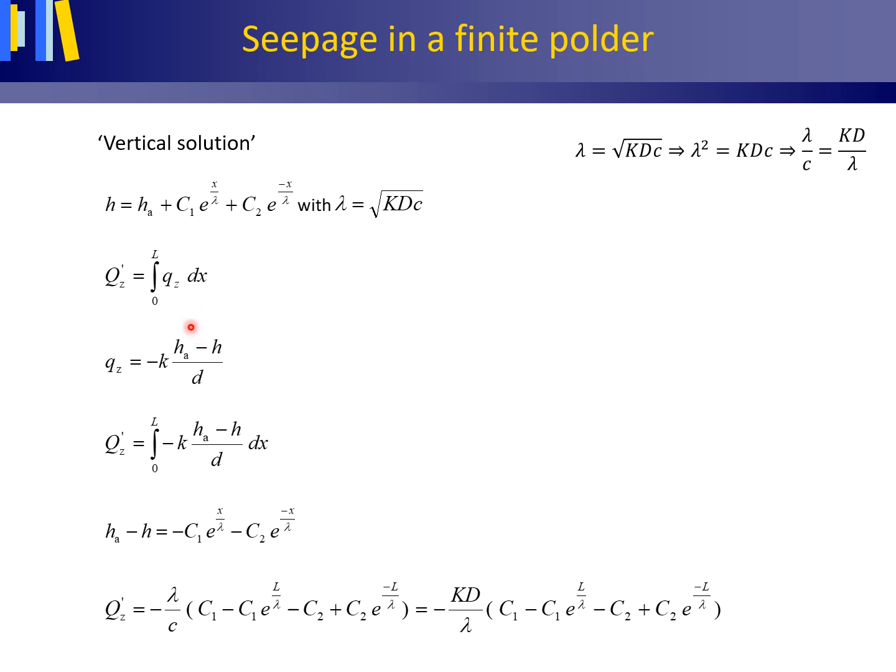So that's your artificially maintained level in the polder, minus the hydraulic head from which the water flow dispatches in your aquifer. So that's this H. And then you divide by the distance. And as water is flowing upward, this distance is a positive number. So you insert this into this equation, and this is what you get.